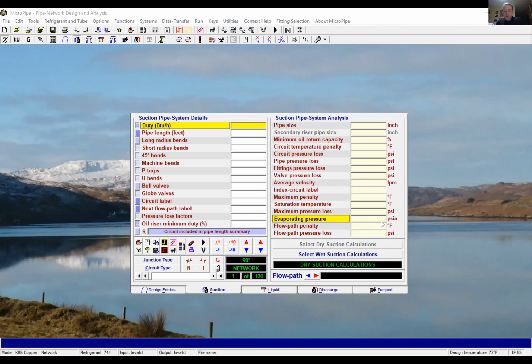There is an argument. I know some designers who don't account for bends. They don't put valves in. They just reduce the line penalty, and through their experience that works for them. I don't do that, because the software gives you the opportunity to put the bends in and the valves in. And as you can see, it becomes like a subconscious activity once you're familiar and you've been using the software for quite a long time.